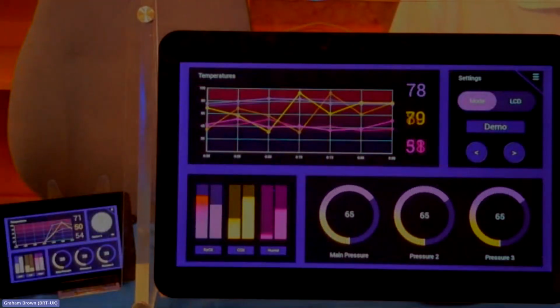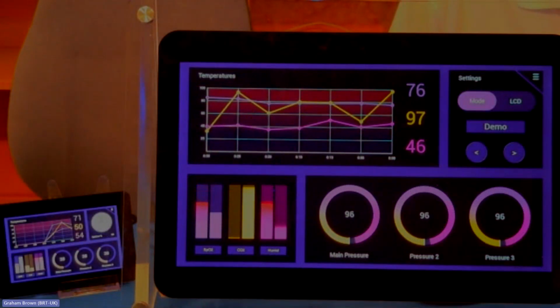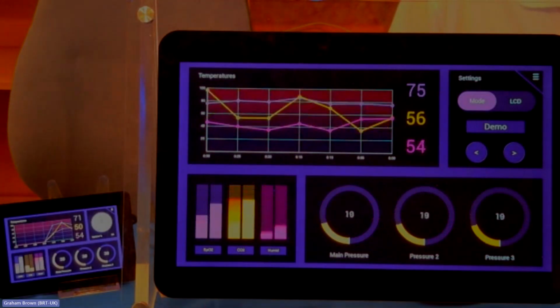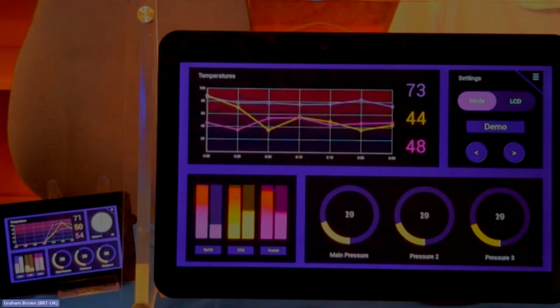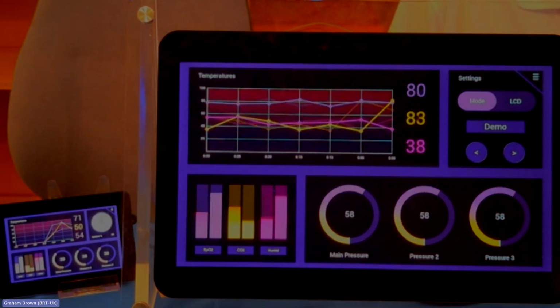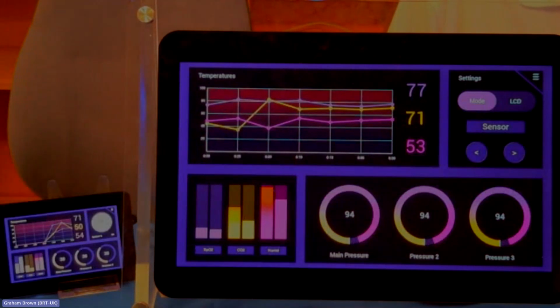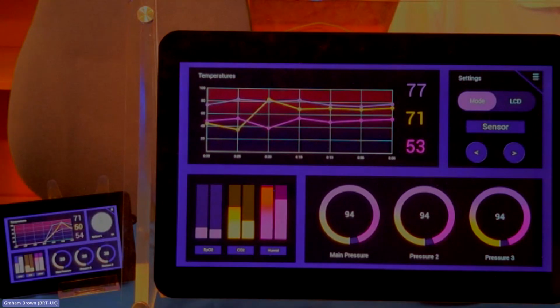And one of the other benefits of Eve is that it will continuously render a screen based on the last display list that you have issued to the device. So for example, if you do not require any screen updates in your application, you can render a single display list, and Eve will continuously draw these items on the screen until you decide that you need to update the screen with some new information, and then you can issue some more commands over SPI or I2C if it is the FT800 to update the screen.